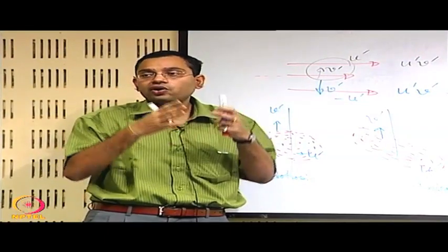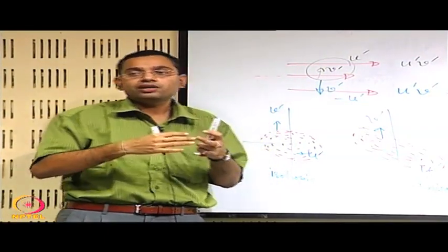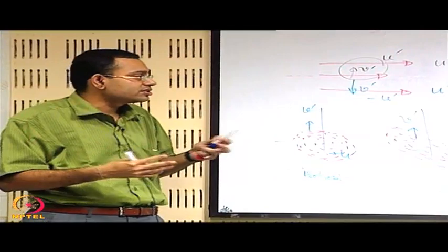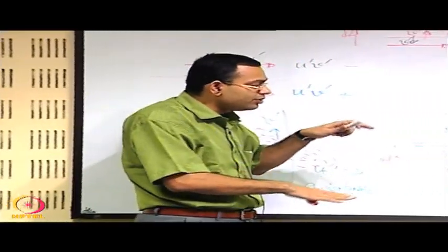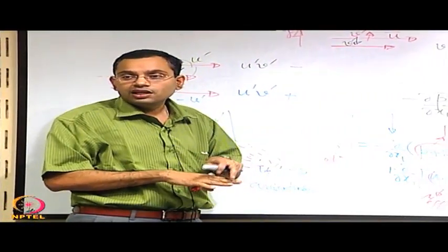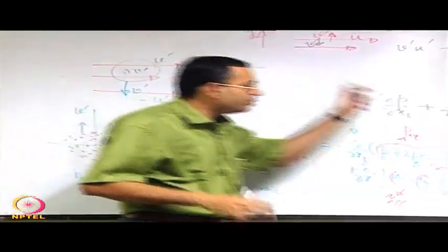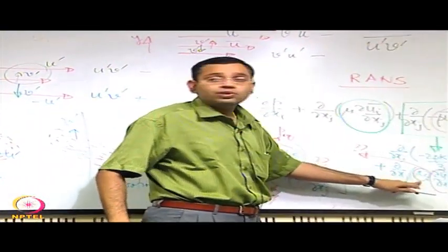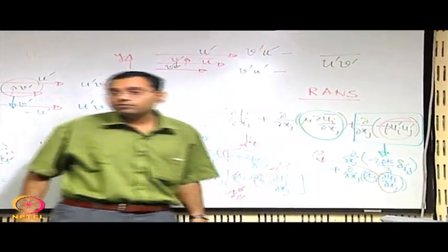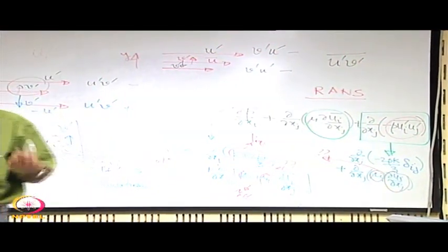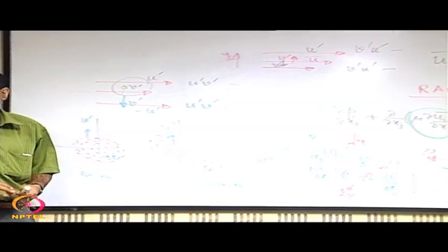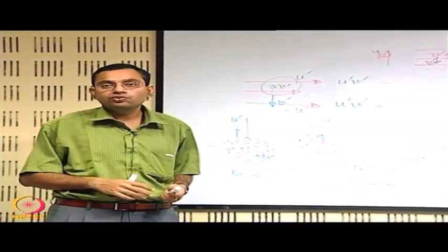Therefore, by drawing an analogy between the exchange of momentum amongst gas molecules and the exchange of momentum between the fluctuation components of eddies, it is possible to have some simplistic description of how to describe this turbulent viscosity, and that may be achieved by a very simple but phenomenal engineering model known as Prandtl's mixing length model, that we will do in the next class.